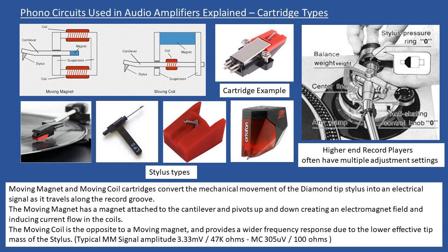Now, what I also spoke about was this mechanical noise. Because the stylus is moving up and down, it will pick up any kind of vibration. So when I think about a motor which is rotating and the platen which is rotating, there will be mechanical noise. So on earlier amplifiers, you normally had a selection which was like a subsonic filter, and you then pressed it, and what the circuit is doing is looking specifically at the frequency attributed to the rotation of the motor and the platen, and it will look to filter it out. On higher end Phono Pre-Amplifiers, which are separate, you may also see this switch in there, but I have seen some where you just don't have anything like that fitted at all.